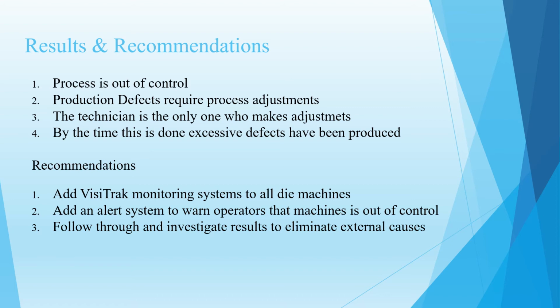The setup technician is the person in charge of making those adjustments, which are currently based off of feel and experience. By the time the technician is able to make the correct adjustments, an unnecessary number of parts with defects have been produced. We recommend the addition of a Visi-Trak monitoring system to every machine in production.